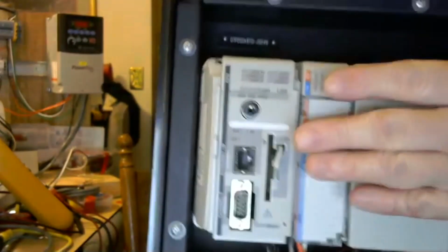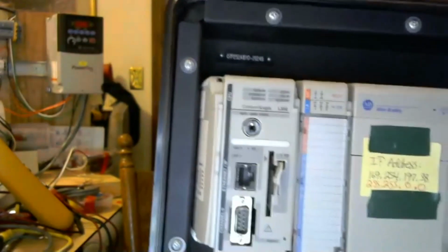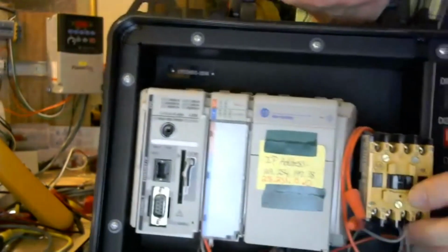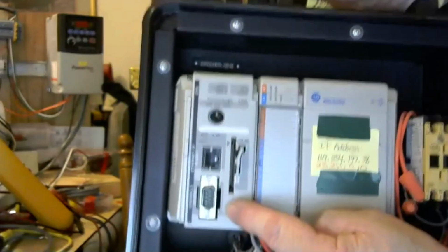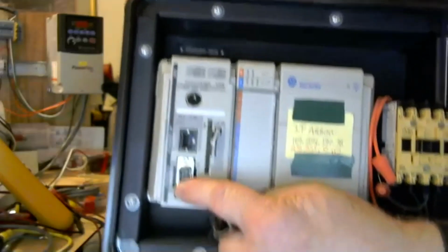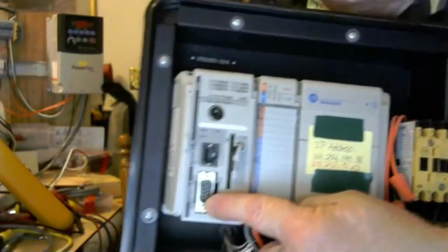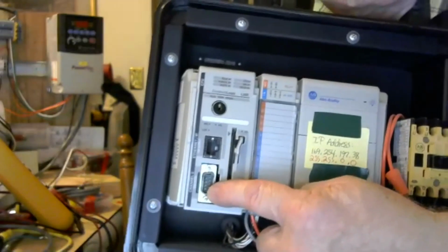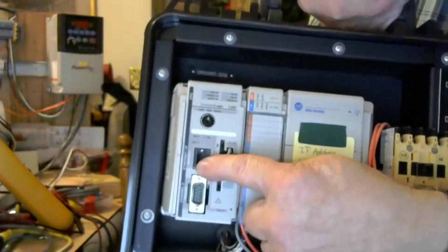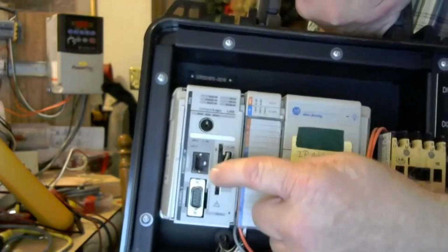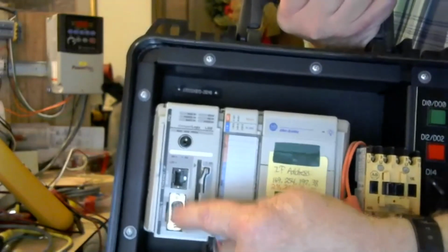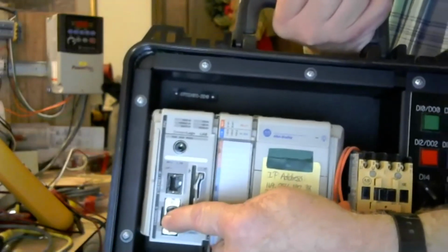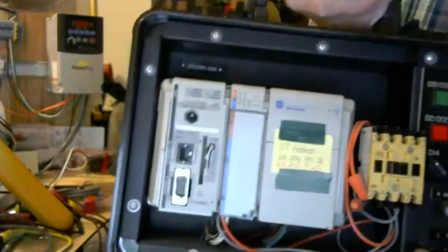This is CompactLogix. It uses Studio 5000, but it's an older version. And if you notice here, it's got Ethernet, but it's also got serial. See that? This is before they put USB on them. So that's got a 9-pin serial port to set it up first. You go in through that serial to set the Ethernet up, and then you just run off the Ethernet. But they dropped the 9-pin serial on the newer ones, and they went to a USB serial to configure the Ethernet.